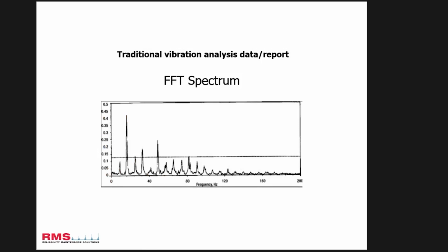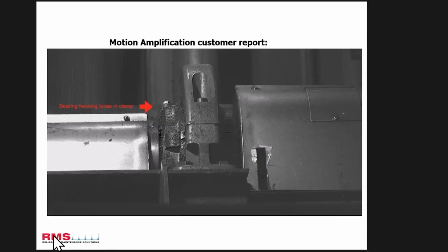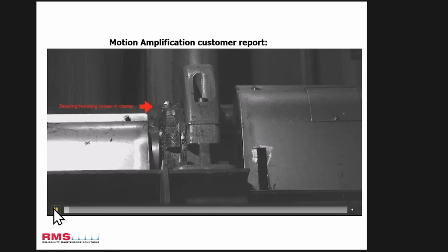And like we said earlier, if I was to go to a maintenance manager with a signature like that and explain to him we've got a looseness in a bearing because that's a looseness synchronous signature, he'd look at me, okay, daft. But then if I played him this, which is the same signature, it's much easier to get your information over rather than show data plots. So this is... Sorry, go on.